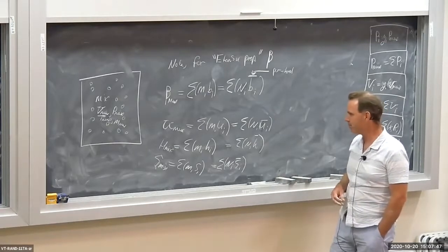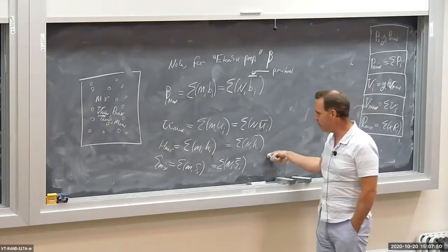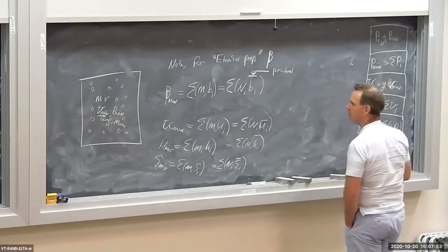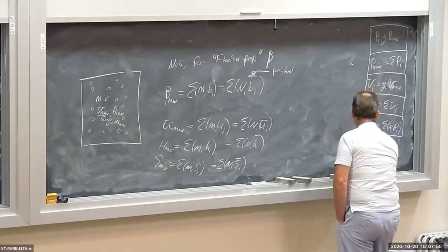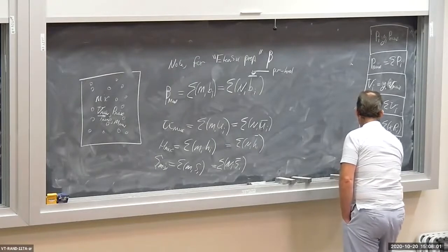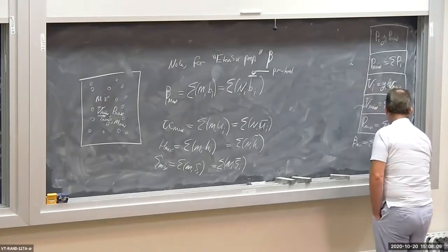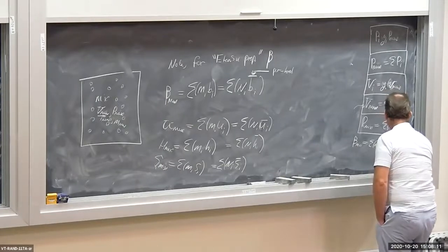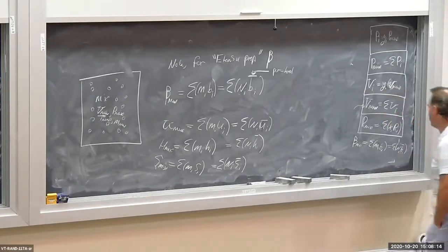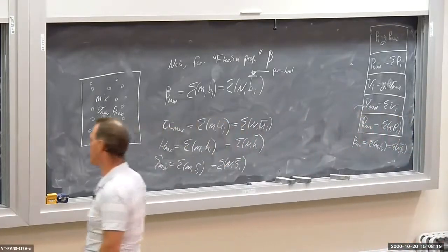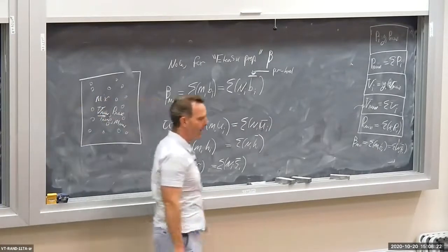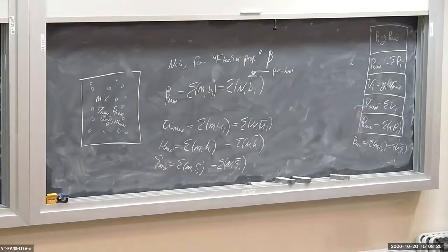Okay? So use these equations here. So I'm going to write this right down here. So beta mix is equal to the sum of the mass of component I times B sub I, summed over all components, or the sum of N sub I B bar sub I, summed over all components. So that's how you calculate properties of the mixture, like internal energy, entropy, and enthalpy.